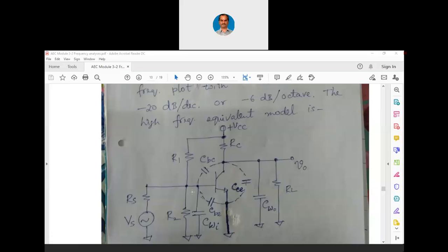Now, at the input we have a wire, and a wire is always two wires together, because with reference to ground there is one signal wire. When they are together, even in the wire, when these two wires are separated by means of an insulating plastic material, even that wire will have its own capacitance with respect to ground. That is how the CWI is shown here.